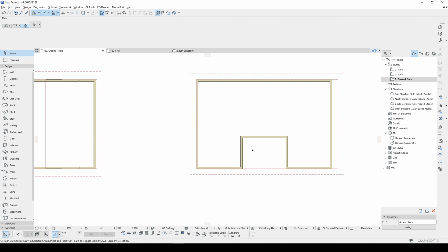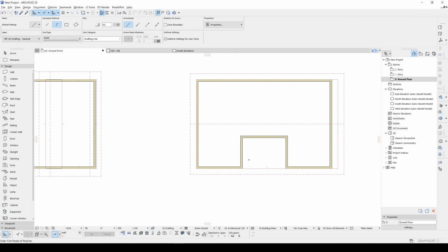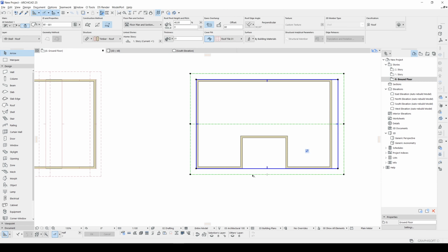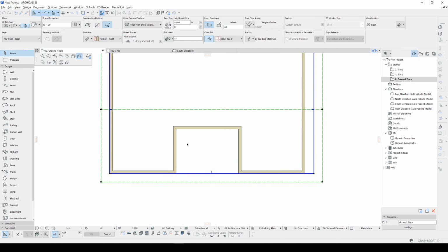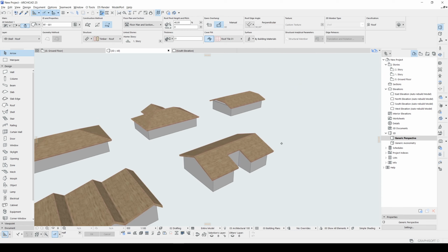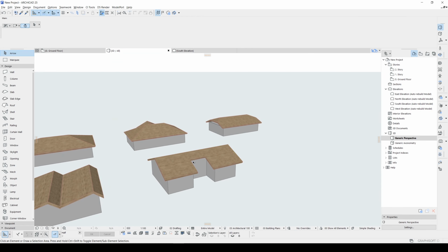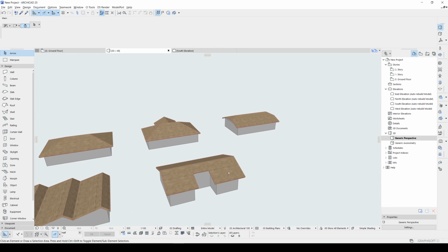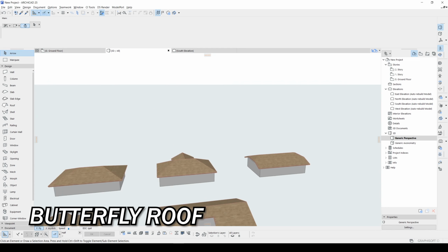And from the floor plan, we will create a hole for the roof. So let's click any edge. Let's click subtract from polygon and create our gap. Something like this. After doing this, you can fix your overhangs value like this. This was drop eaves roof. Let's move forward.